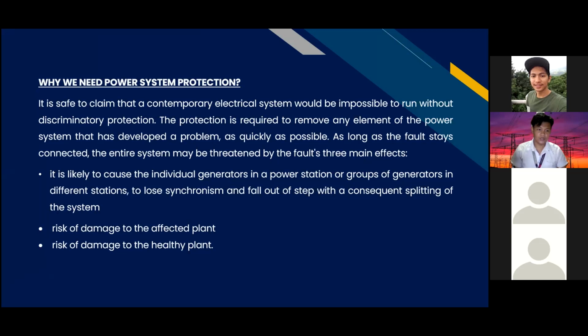First, it is likely to cause the individual generators in a power station or groups of generation in different stations to lose synchronism and fall out of step with a consequent splitting of the system. Second, risk of damage to the affected plant. And third, risk of damage to the healthy plant.